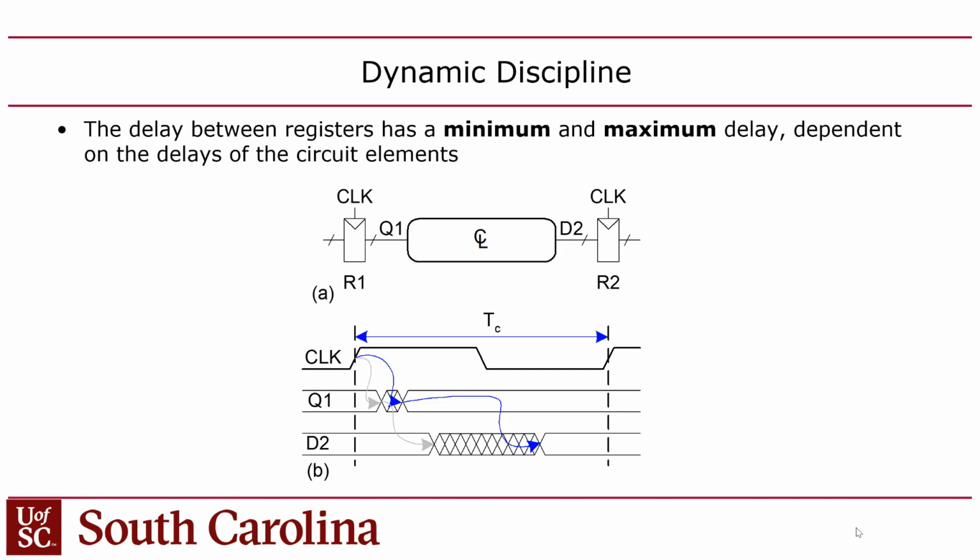Yes? If there is a possible violation of hold time, doesn't it signal that there's probably something wrong with your design and you should restructure it? You shouldn't have to do anything about hold time violations. However, that being said, I have gotten errors from, particularly, the Xilinx tools. I get hold time violations all the time. And I usually don't know what to do about it.